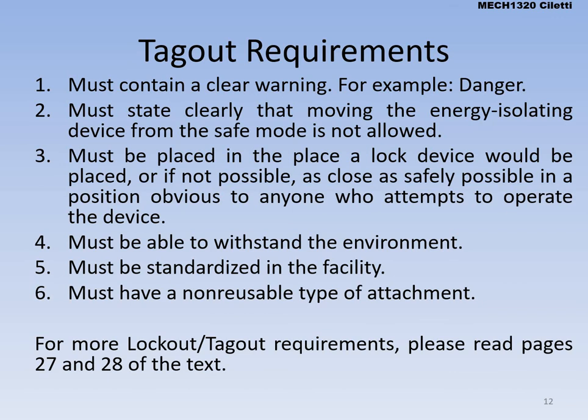Tagout, we see lockout tagout. Sometimes the person's information is on the lock. Tagout, we use those for pneumatic devices, all right? We've talked about this on the 870 trainer. You can tag it out by using a zip tie or the tag through it, or you put the lock on the pneumatic piece so that air can no longer go through there. It has to state clearly why that energy device is not allowed. You're not necessarily going to put a master lock on it, but you're going to put the tag there, so that's tagging it out.